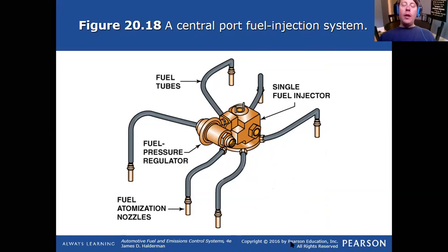It had this style injection system on it, and what happened is the customer shut the car off and all of the fuel, every time they were shutting it off, was just running out one of those injector nozzles. The little check valve was broke, and this injector was holding fuel pressure from the tank, and every time it shut off, it was dumping all that fuel. And it may have been a combination between that and the actual lines cracked.